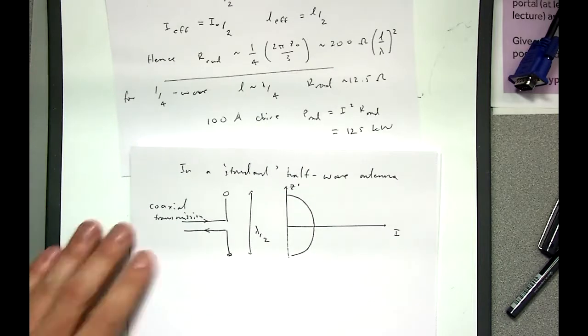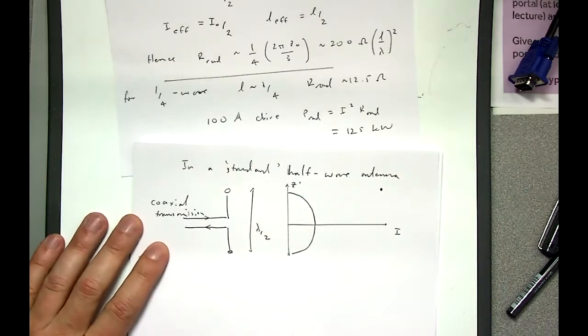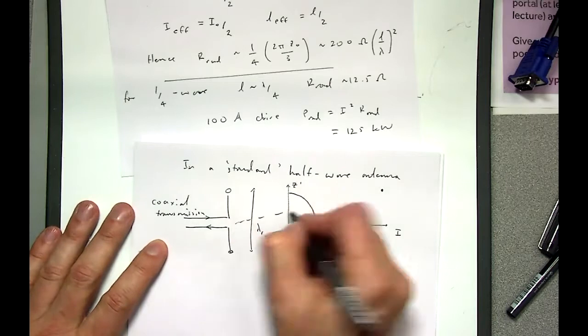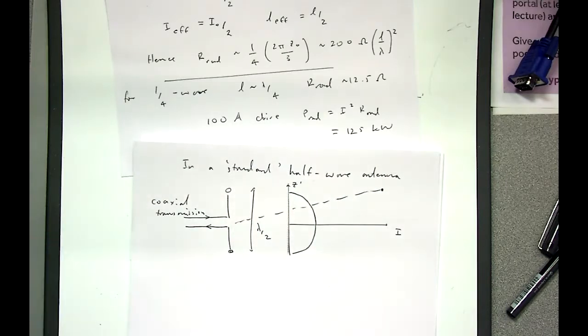We wish to work out what the total power received at some distant observation point is, and we should really now put in our statement that, remember, for a Hertzian dipole the power observed depends on the angle, roughly a sine squared of the angle, shouldn't it? So it should depend on this angle theta.